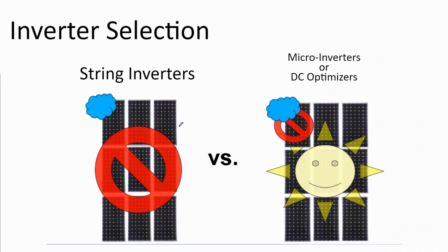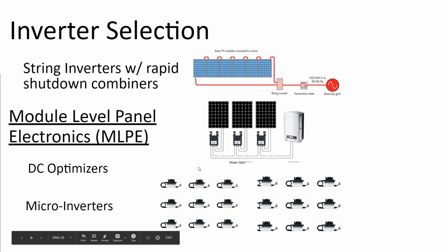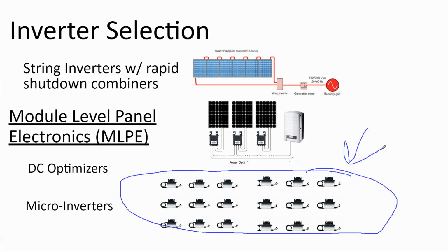And that's good, because what fails is the microinverter itself or that power optimizer on the roof itself. Now that you're putting all of these boxes up on the rooftop, you're inserting a lot more failure points in a place that is dangerous to work on, which is the roof. And so this was a controversial issue as to whether or not you should use microinverters, because while they do have some benefit for shaded rooftops, the question is, should you always use them? Are they so much better that they're worthwhile to use all the time despite the increased cost?